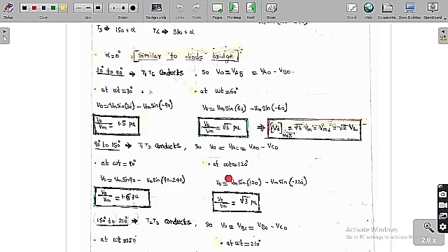Similarly, at omega t equal to 120, I want to find the value. V0 is equal to Vm sin of 120 minus Vm sin of minus 120, using the same principle. If we solve this, we get V0 equal to Vm into root 3, or V0 by Vm equal to root 3 per unit, and this is the maximum value. This is the peak value of the line voltage, or root 2 into VL. So we have drawn the graph for 90 to 150 also.